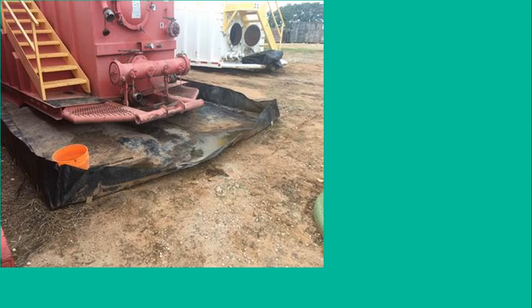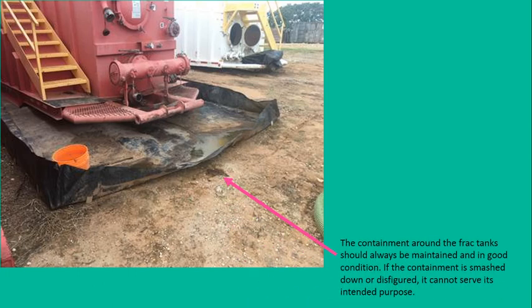This is an example of a horrible looking secondary containment. Containment around frac tanks, containment around drums, totes, whatever, needs to be maintained in good condition. If it's smashed down or disfigured, it can't serve its intended purpose, which is obviously an issue. This is the type of thing you'd be looking for in your weekly and monthly inspection logs. Are things set up to serve as secondary containment in good condition? And if not, you need to figure out how to fix it.